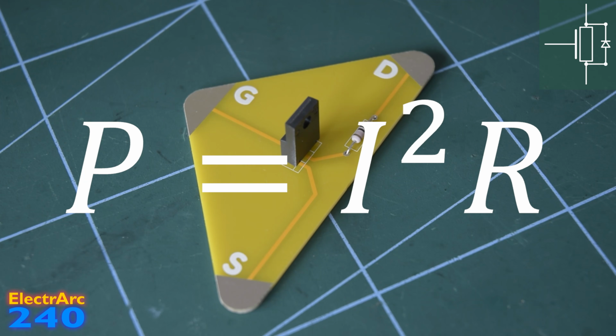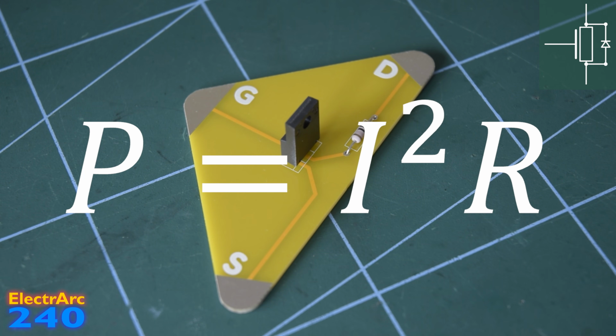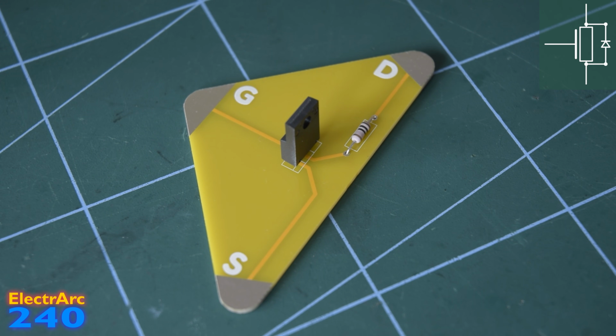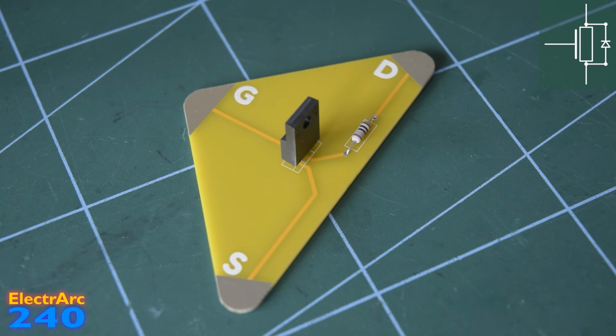So that means for this particular MOSFET, if we had 50 amps of drain current flowing through the channel, we'd have conduction losses of 5 watts, which may not sound like a lot considering there could be hundreds or even thousands of watts being controlled by this MOSFET, but it still needs to be dealt with, and how easily we can get this heat from the MOSFET's channel and out into the air is dictated by thermal resistance.